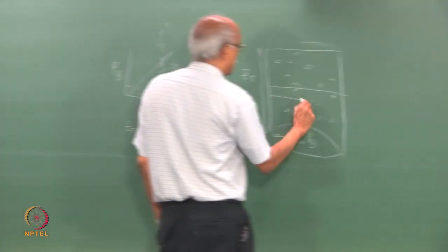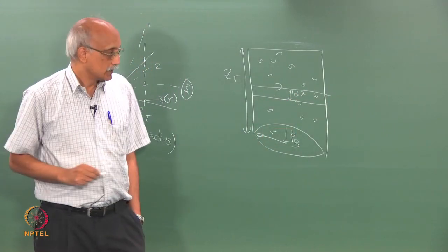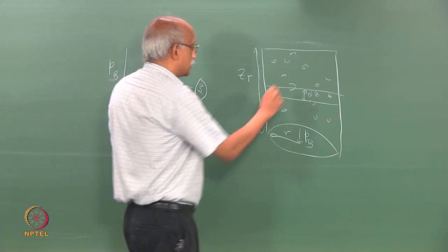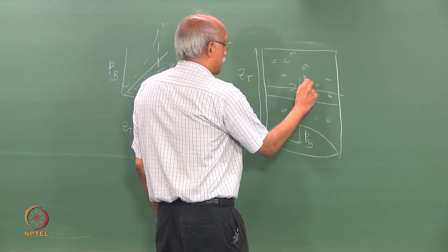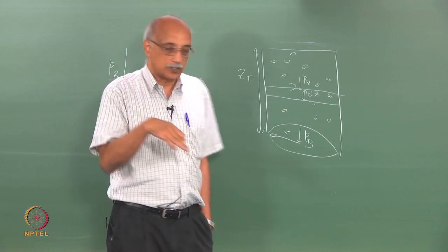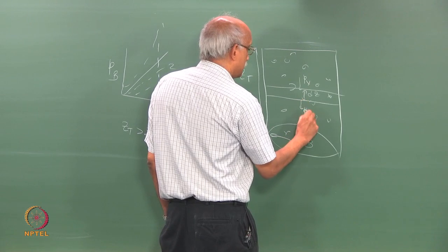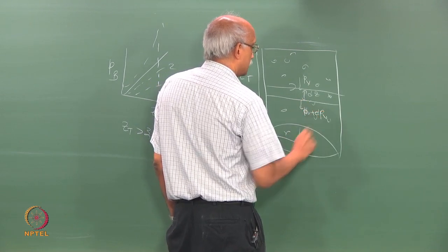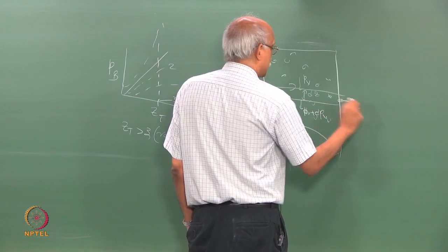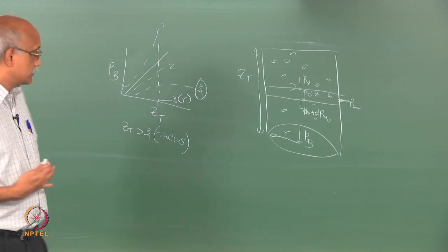So, let us take that you take a small section, some dz let us say, and you just do a pressure balance around that. So, let us say that here you have a pressure PV, vertical pressure or applied pressure, and this pressure here becomes PV plus some dPV, and let us say that there is a corresponding PL or lateral pressure that develops on the sides.